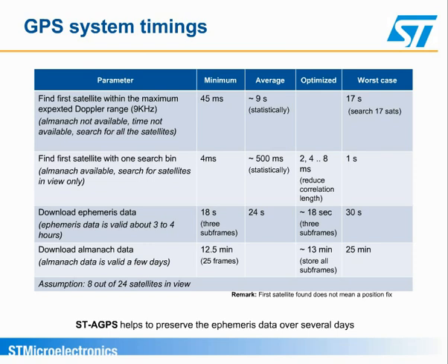We have seen the transmission rates and the signal protocols from the satellites. If we are starting the system, it takes 30 seconds to download the satellite data for the ephemeris data. Downloading the almanac from a satellite takes 12.5 minutes. If we do not have the almanac data, it is called an autonomous start, and worst case, it takes up to 25 minutes to receive the 25 frames twice if we missed one bit.